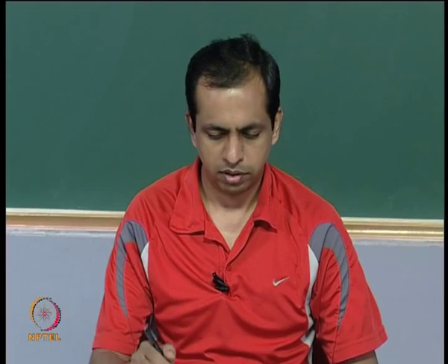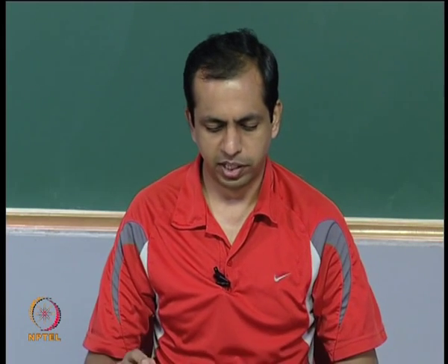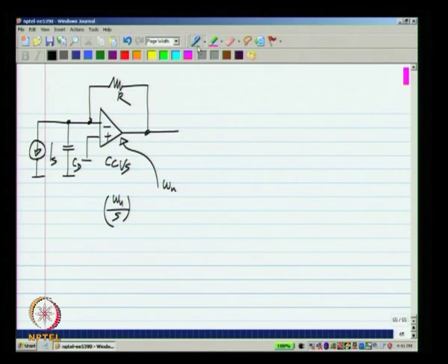It turns out you have to consider the effect of the DC gain only if you are looking specifically at the accuracy of the amplifier around DC. If you are looking at stability and other things, which we are going to look at, you can usually model it as an integrator and get away with it. So, what will be the voltage here?